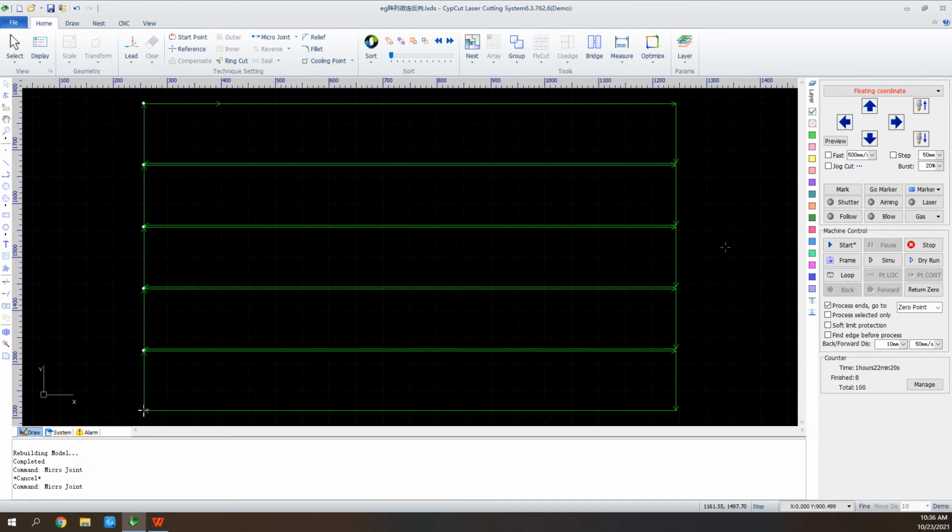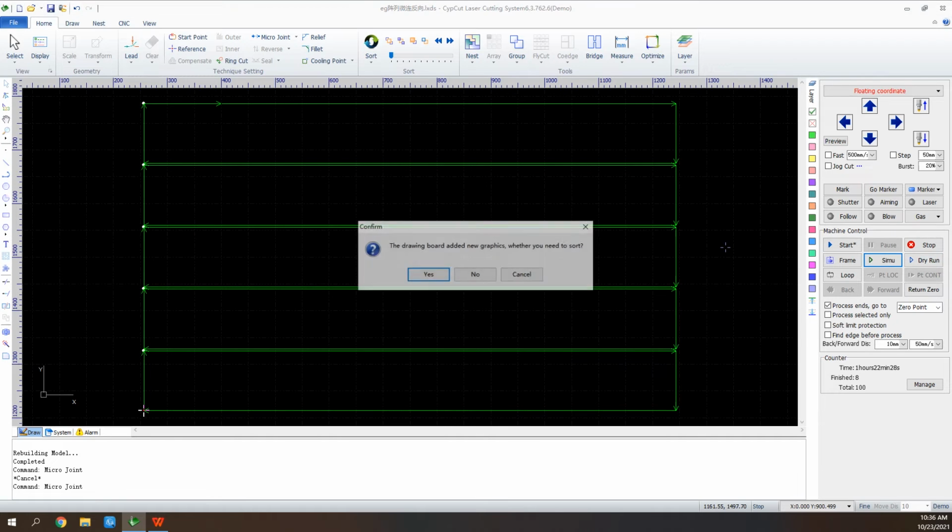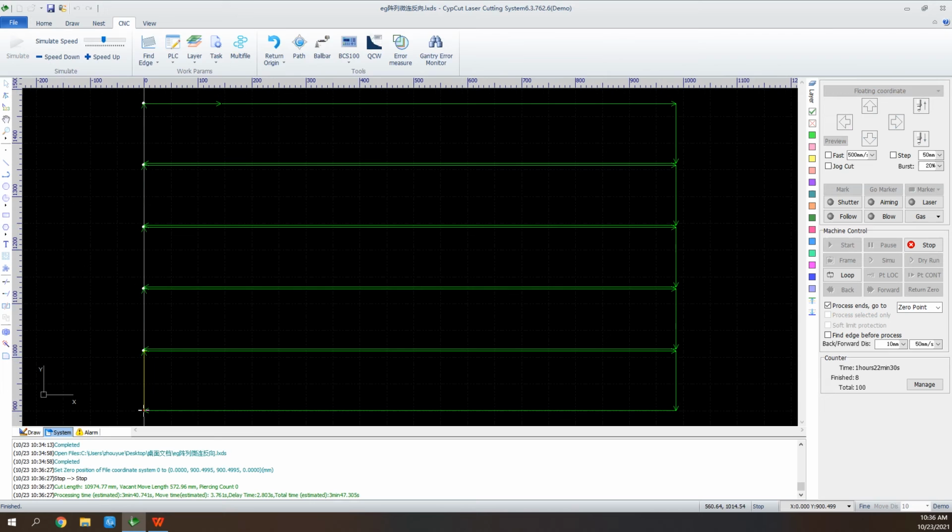And besides, as the default cutting path goes clockwise, when we come to the bottom line of the second oblong, the sheet will vibrate for lack of support.